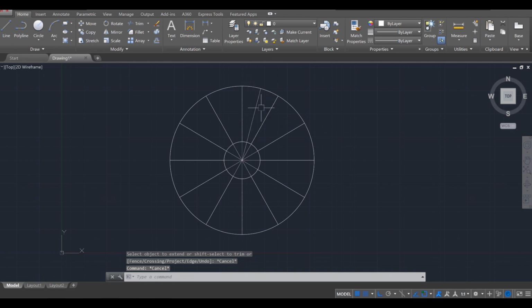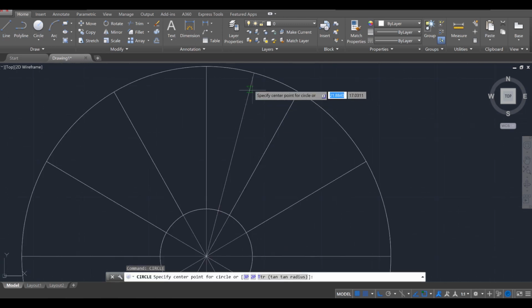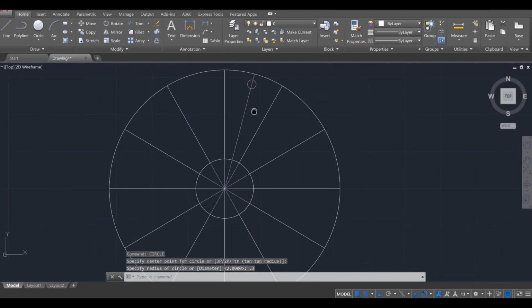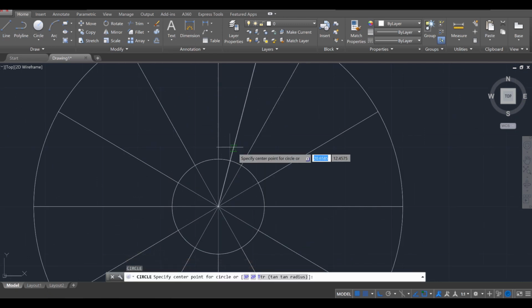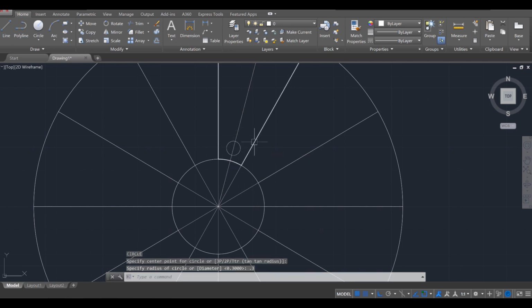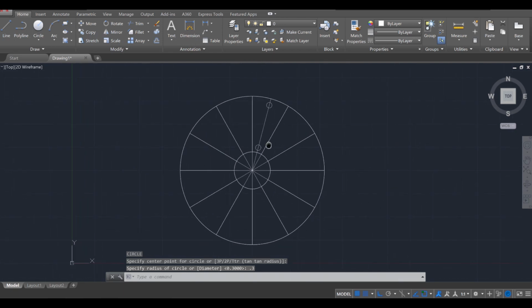so that you've drawn the line in place, which will allow us to draw a post in the direct center using the circle tool. So circle, enter, and then right near the edge of the step, I'm going to draw out a circle of, let's say, distance 0.3, enter. Okay, so just a small little post. Let's also add a post to this area over here. So I'm going to draw a circle again, and right at the edge here, another post of 0.3, enter. So we're left with 2 posts.